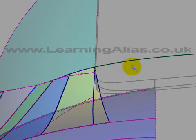With that curve established, we know that we can build a surface from the end patch when we've got it to create our deck from. That's the deck secondary surface. So we don't want this piece of curve on surface here, so we can detach it at that point there and do that very accurately, and then delete it, and then reproject this curve, or project this curve here.